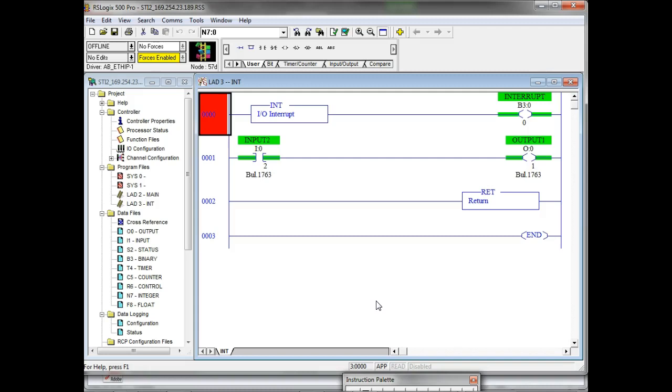What we usually do, and this is what I recommend on PLC 3, is set up your tag table before you even start doing what? Program. Set up your tag table, because the RSLogix software gives you the tags you're going to use. Go ahead and set that thing up, and then from then on, you're just typing in words instead of trying to remember what IO is. So all these advanced PLCs give you the ability to set up a tag table before you program. Here we call them symbols. The other more advanced PLCs call them tags.